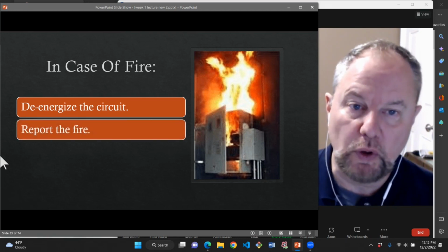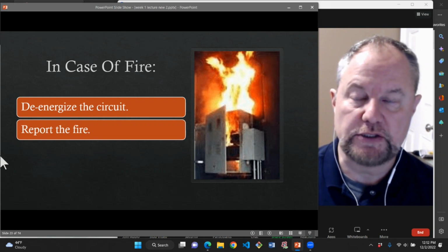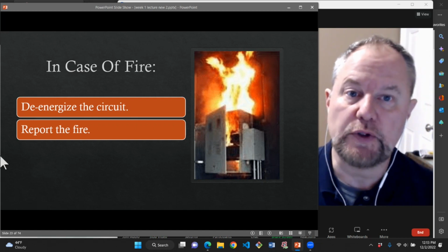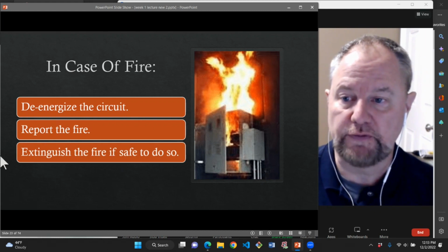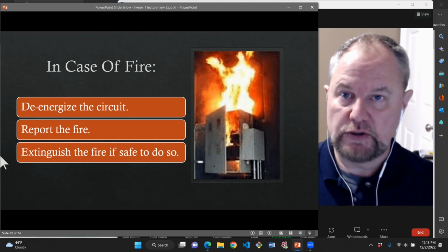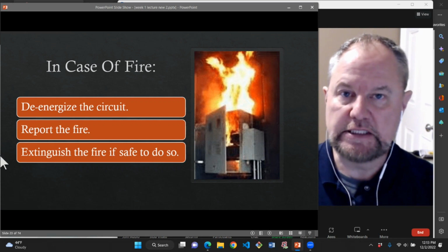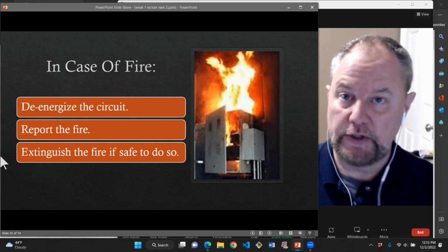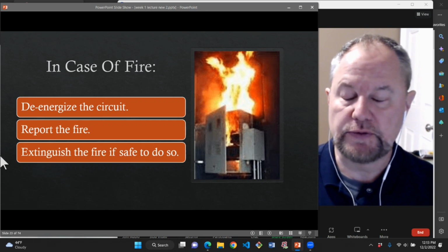Obviously, you want to report this to somebody. Make sure everyone's aware, especially the supervisor, so that any emergency action can be taken. Again, communication is super important. And then if there's a fire extinguisher nearby for electrical fires, grab that and try and put it out if it's safe to do so. If it's a dicey situation, you are more important than the equipment you're trying to protect. Run for the hills. If it's bad, don't stick around. But if there's an extinguisher nearby, use that and try and put the fire out.